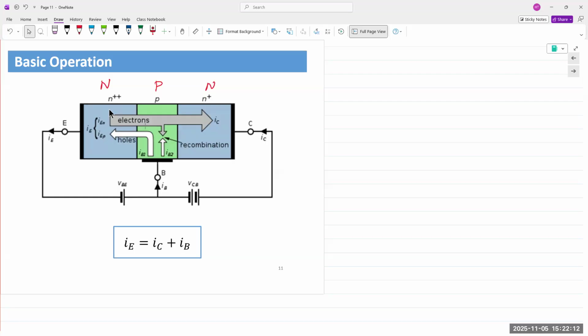So electrons and holes will recombine, give off excess energy, and an electron-hole pair disappears. But there are plenty of electrons and not enough holes to go around. And that is, of course, on purpose. The base is very lightly doped, right? So there are all of these electrons just hanging around in the base, with nothing to do.